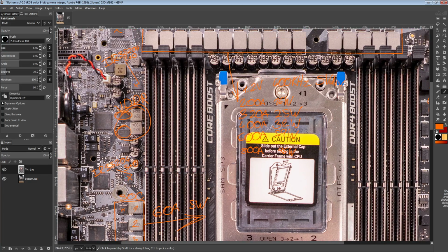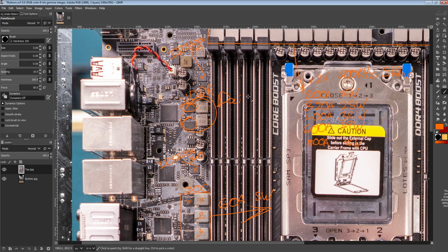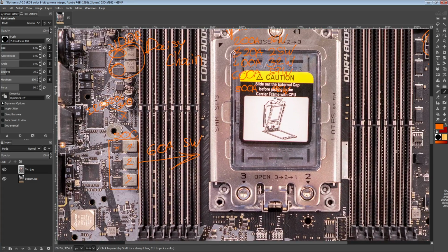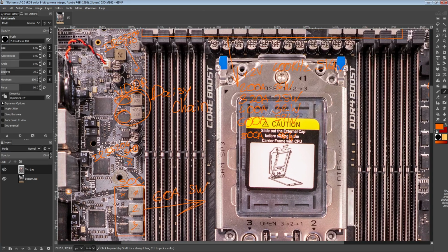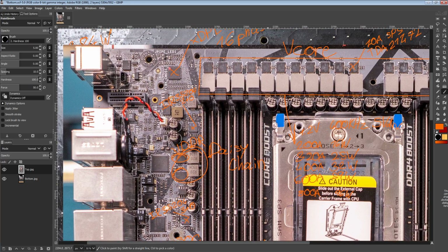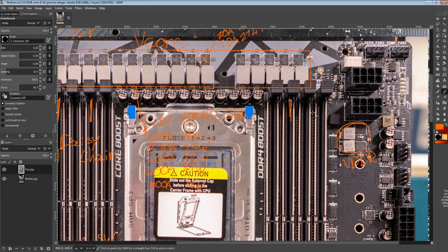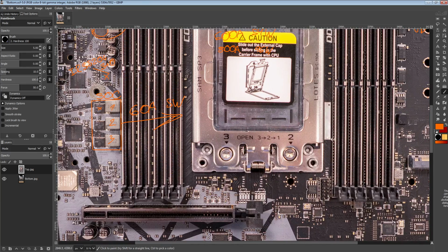So anyway, for the actual memory topology here, we are looking at a daisy chain, which is just standard for the Ryzen memory controllers. It just seems to be that the Ryzen memory controller plays best with this topology. So of course MSI is still using it, and I assume all of the TRX40 motherboards are using it as well, because it just seems to work the best for all memory configurations in general, and it does give you an advantage if you are only populating those 4 DIMM slots, which the motherboard also helpfully tells you directly on the motherboard. I do actually appreciate that.